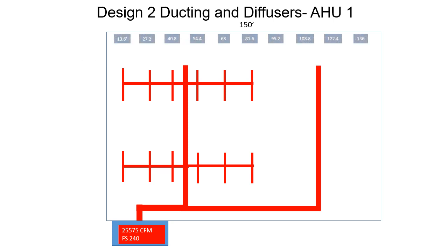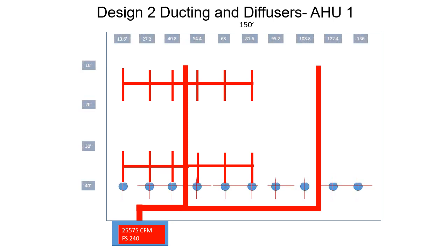Okay, this process is about the same. Here it's only shown the coordinates, so how to arrange your diffusers according to these coordinates, so that when the men come for installation, then they can refer to your drawing and see where the diffusers should be.